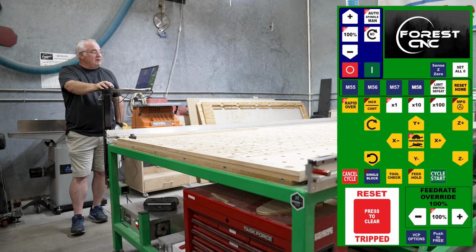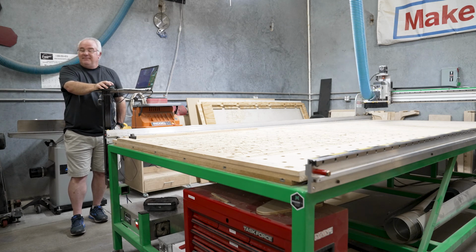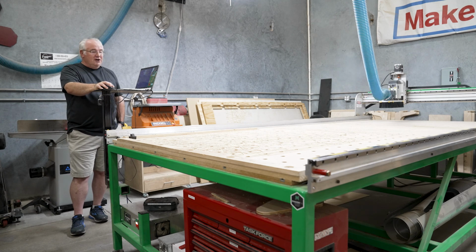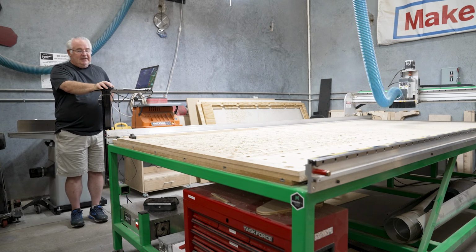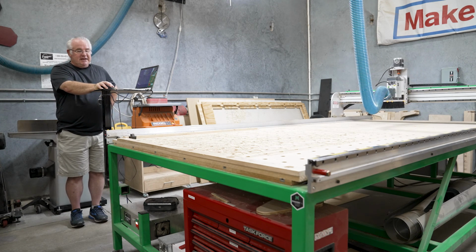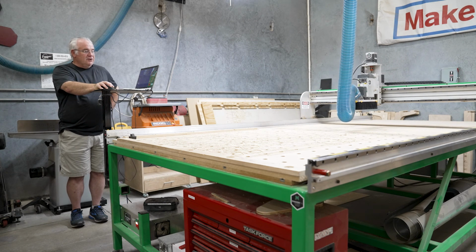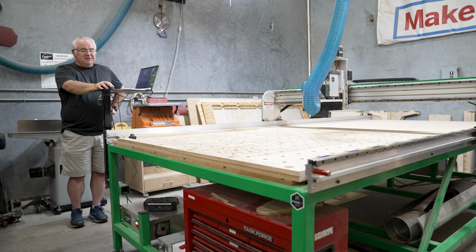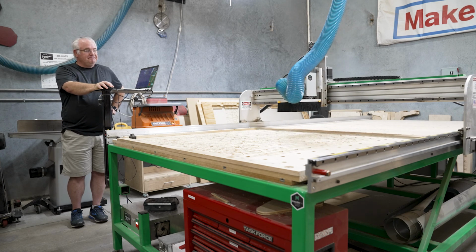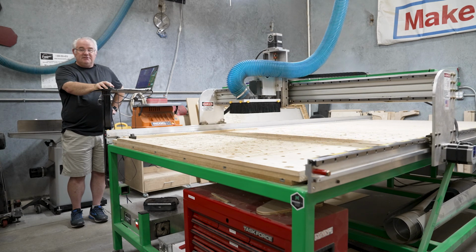So if I'm pressing and holding X plus, you can see the gantry is moving really slow. If I turn that light off, that moves much faster. So for purposes of getting it to jog up here so we can put the bit in, we're going to keep it in rabbit mode or fast mode and get it up here. When you're setting your home position for your job, as you get close to that home position, you'll want to turn it back to turtle mode, slow movements, so you can be a little bit more precise in setting that position. So all I'm doing is pressing and holding. It's very responsive. As soon as I let go, it stops.